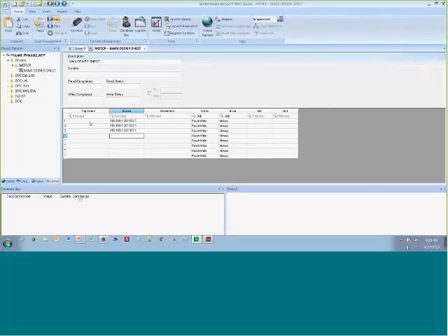Now, one thing that I've done is I've actually copied this entire worksheet into Excel, used the find and replace, and then come back in here and pasted that in. But instead of doing that, another concept that you can do is something like this. Instead of using the actual IP address or the station address, you can put a tag name in here inside of curly brackets, not parentheses, but inside of curly brackets.